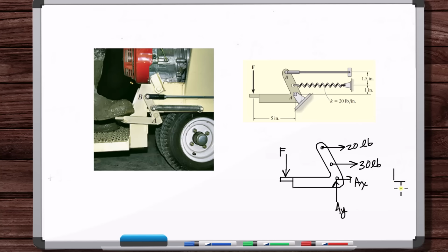That's another thing you want to do with the free body diagram. You want to put your positive coordinate directions. That's important too. Make sure you put the positions of the forces, the dimensions, in the positive coordinate directions. But we don't need to put the z-axis because we know it's part of the right-hand rule, so we know the z-axis is going to be out of the page. We use the right-hand rule, x to y, push x to y with the right hand. But yeah, you just put these in the positive directions. They're unknown forces. The final answer will tell you if you got these force directions right. If you get Ax equal to a negative number, then it's going to be that magnitude in the opposite direction of what you put.